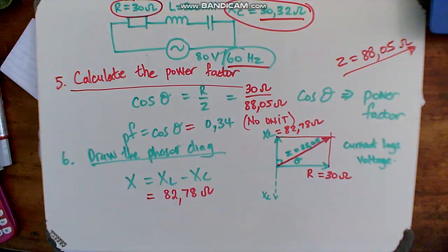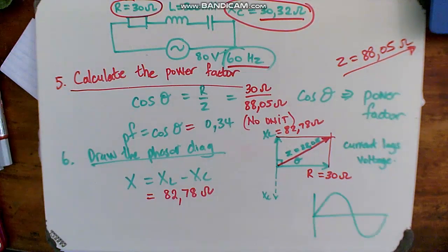So in this question, they're not asking to draw the waveforms. I'm just going to elaborate. So do notice that the V will start at 0, and the current is the one that would be lagging in this case, right? So remember, with inductors, it causes the current to lag. So the current lags the voltage. By what angle? It will be the angle theta.